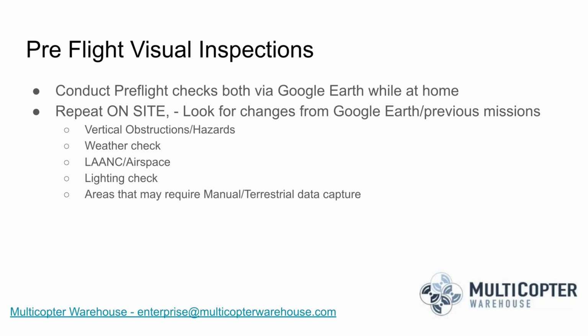What's the best time of day you find to run mapping missions? Another great question. So for those folks who are planning their own missions, usually that window between what I'll call 10 and 2, when the sun's at its highest altitude of the day, you'll have fewer shadows at that point in time. But depending on what you're mapping and modeling, you may not have shadowing issues in all situations. And so whenever you can get good quality photos is really the best time. If you can get a good quality photo, you should be able to get a good quality end output from Pix4D.